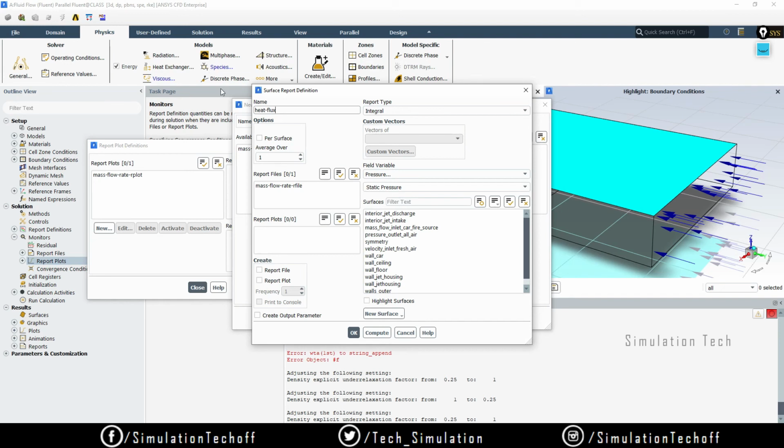Or else you can say it as an inlet heat flux, or a heat flux anyway. So the variable should be wall fluxes. The specification is total surface heat flux. Okay, in which region do you want to view that? I want to view it in the wall region.